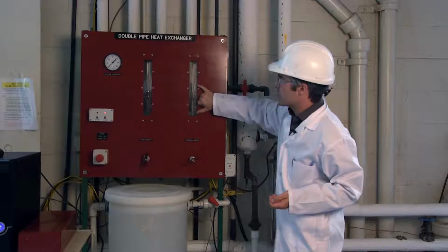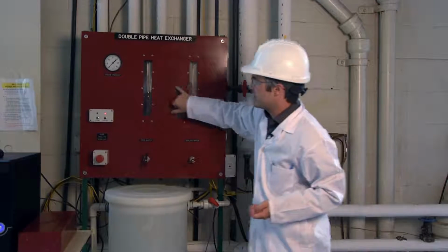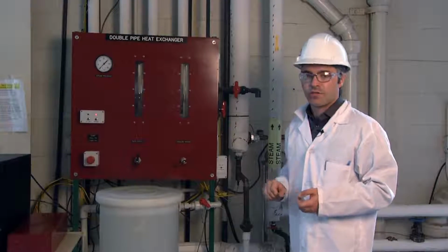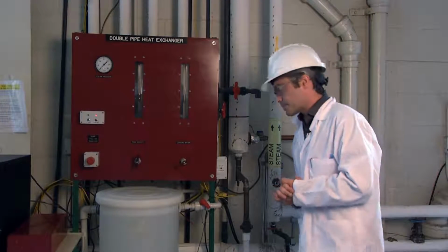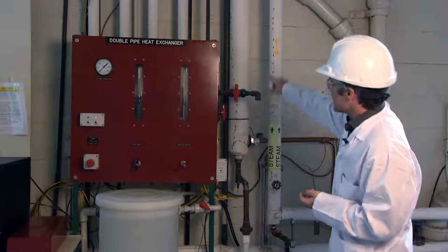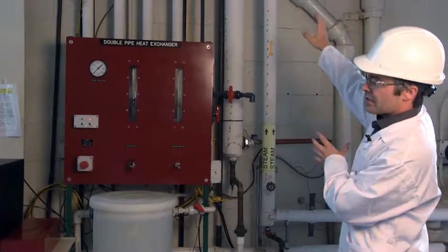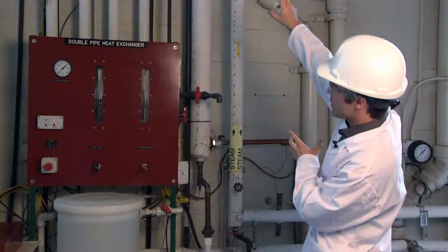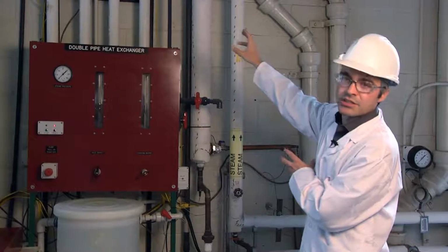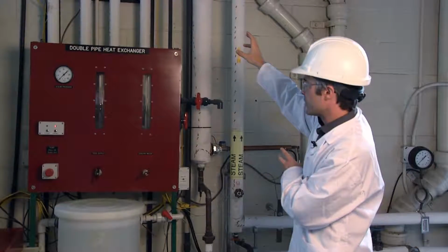Make sure that you take a look at the units and see what it's corrected for. This will have a bearing on your overall energy and mass balance. Now we're running water through the entire apparatus. The cooling water is moving counter current, but we are currently not heating the unit. This is the last step that you should take in order to run the operation.